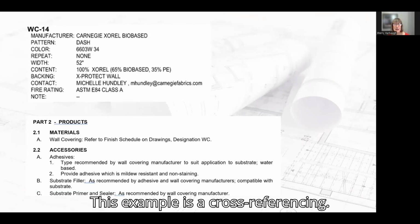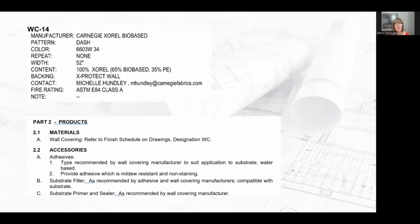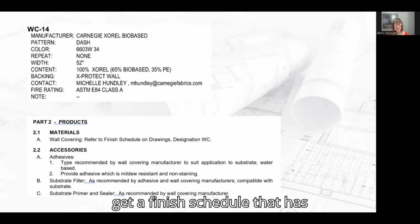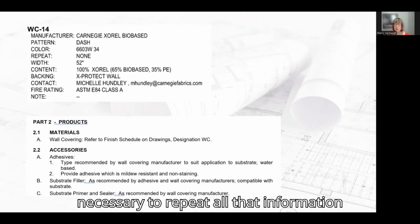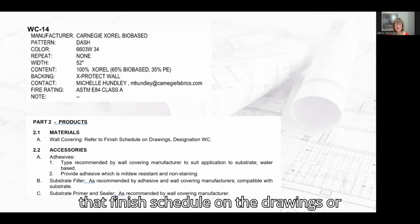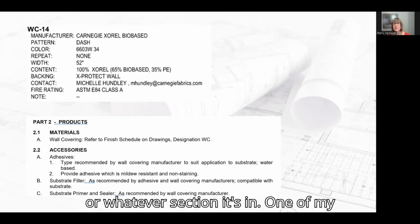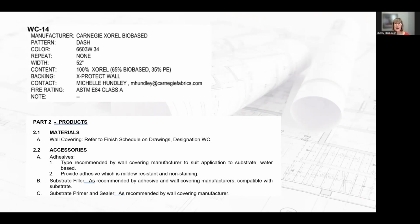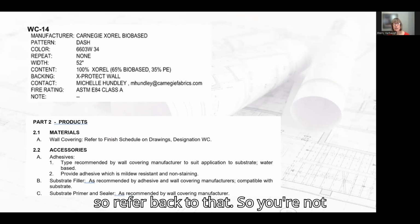This example is cross-referencing for wall covering. Oftentimes we'll get a finish schedule that has all this information on it. So is it necessary to repeat all that information in the specification? I vote no, and I refer back to that finish schedule on the drawings or whatever section it's in. One of my clients puts it in Division 9. So refer back to that so you're not repeating things.